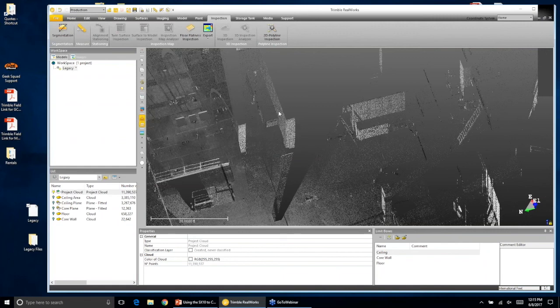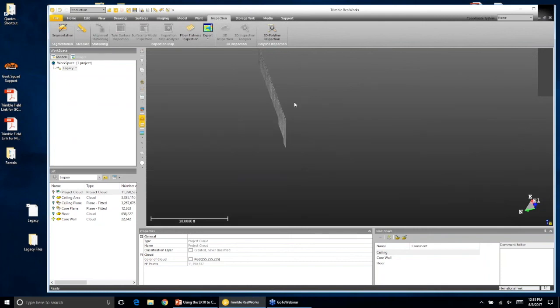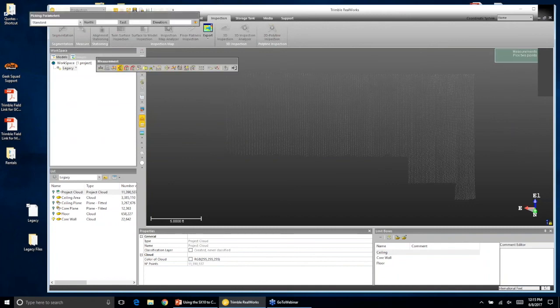So how do we actually measure? With the 3D laser scanner, we can hit the scan. We can segment out the information that we need to. In this case, I've done that here. So I'm going to isolate just this wall. If I really wanted a lot more information, I could, but the density on here is fairly decent. I can pull measurements just like we're used to. So it's telling me this is 14 feet high.